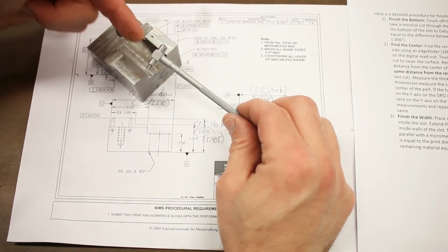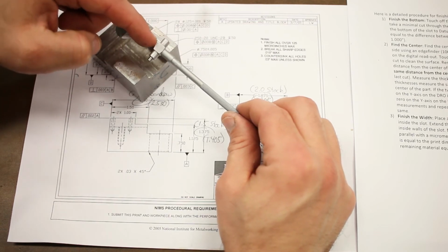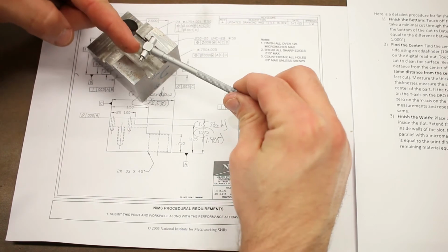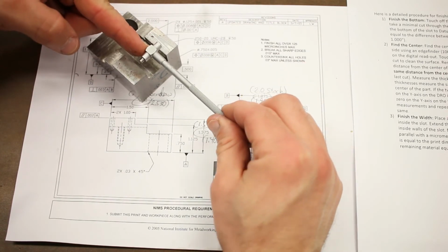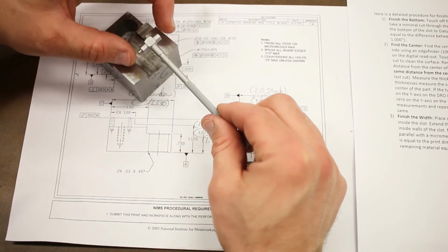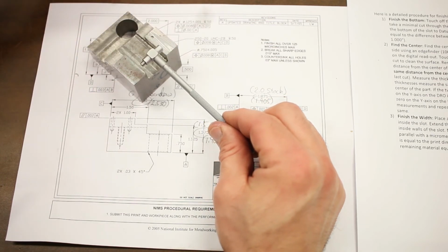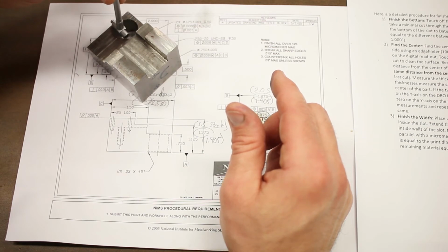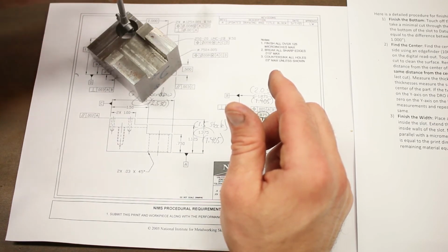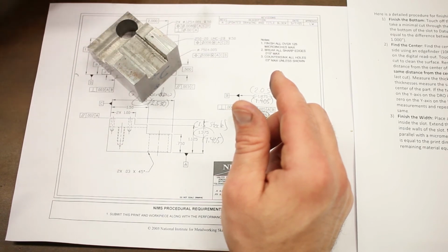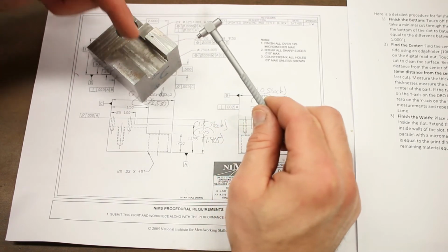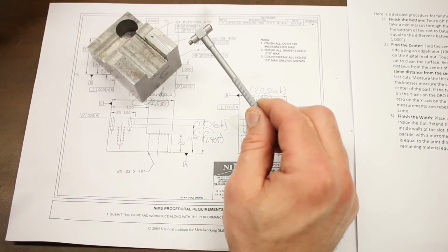The problem with this method, though, is that the telescoping gauges really only work for inside diameters. The way that these work is that you rock them through the hole and they naturally conform to the inside diameter. Like on this hole here, they find the largest value this way and the smallest value this way, and that is the true diameter of that hole.